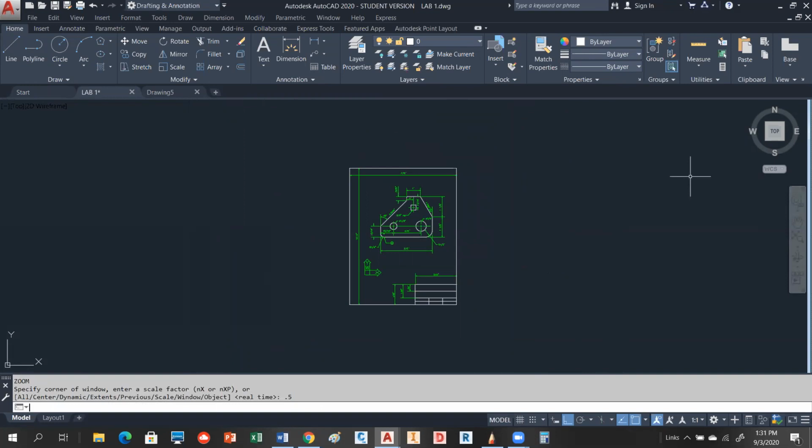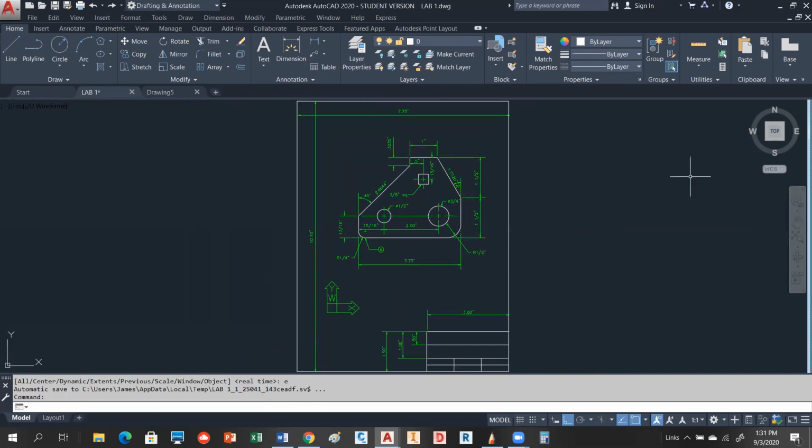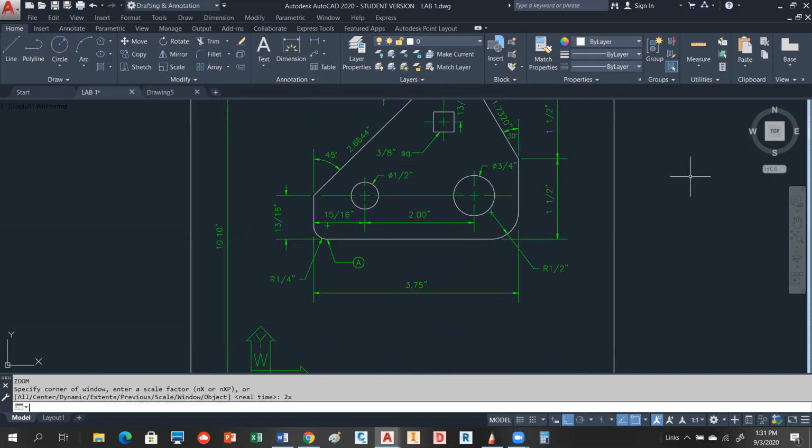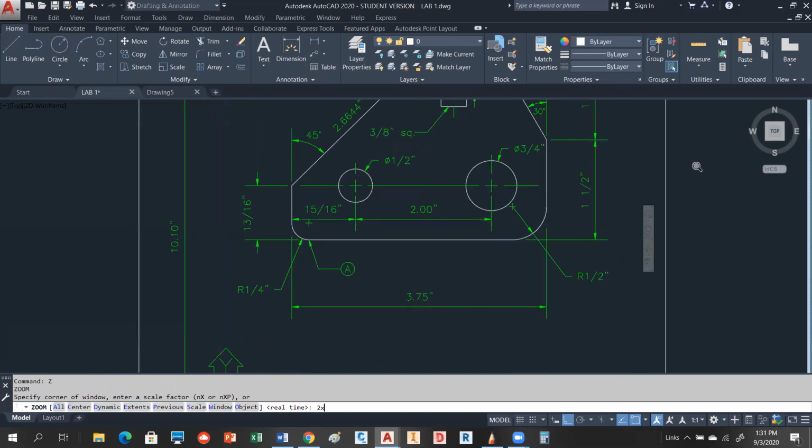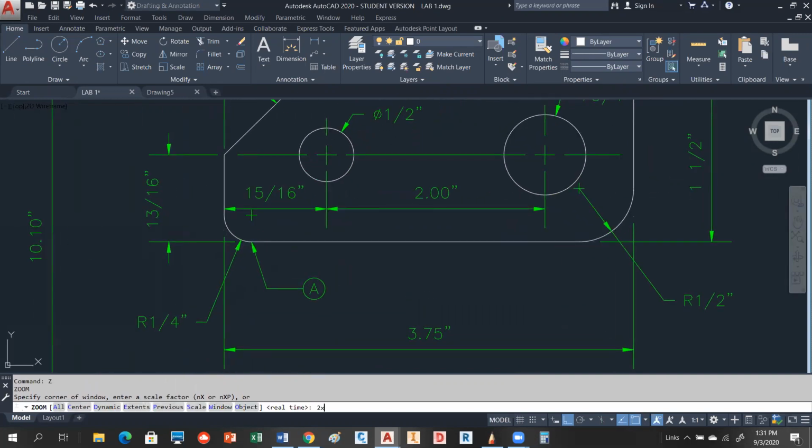This isn't a very useful zoom typically for me. So let's go ahead and do a zoom extents. What I do like to use is the zoom times the current display. This is neat because I can say Z enter 2x. So that's half as big as the current display was. Z enter 2x again, Z enter 2x.